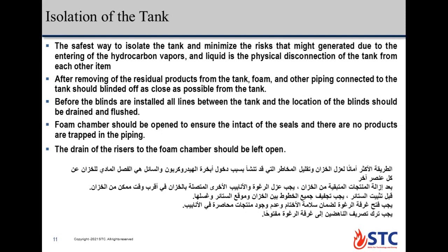Again, the safest way to isolate the tank and minimize the risk that may be generated due to the entering of the hydrocarbon vapor and liquid is the physical disconnection of the tank from each other item. After removing of the residual product from the tank, foam and other piping connected to the tank should be blinded off as close as possible to the tank.